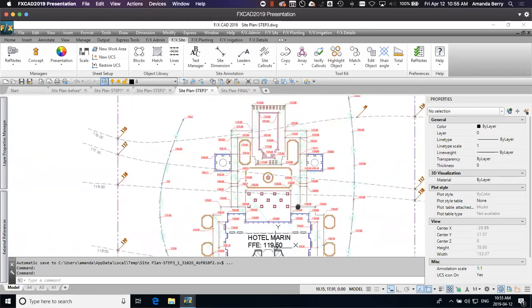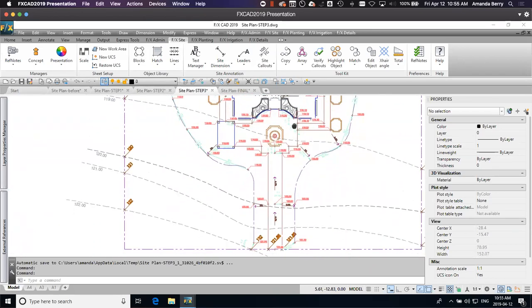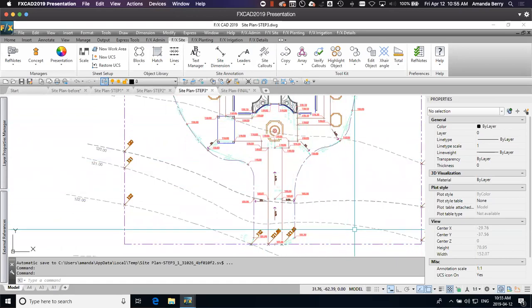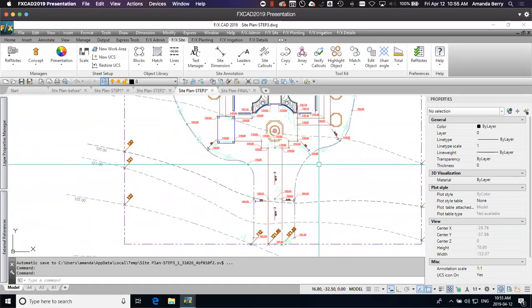A big consideration when sheet draining is that you don't want large areas to sheet drain over a pathway. Generally, I learned that mostly because water freezes up in Canada, but I think it's a good consideration in all climates because that could easily lead to a lot of debris and soil sheet flowing.